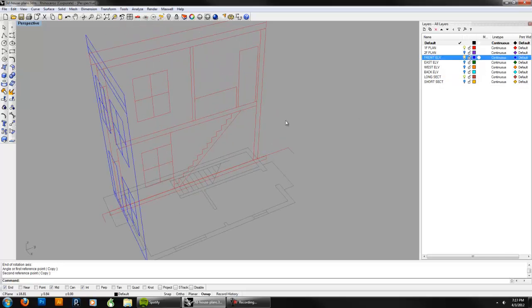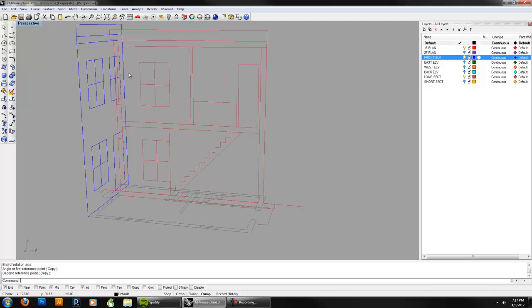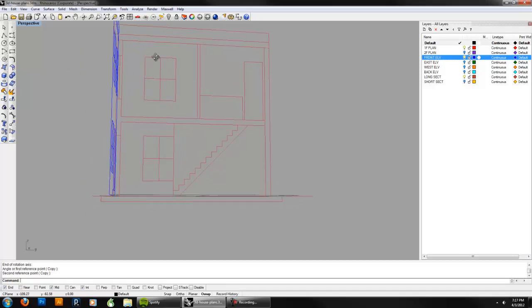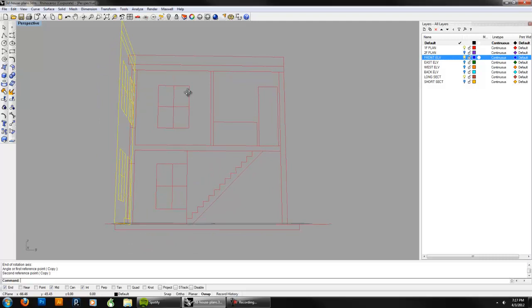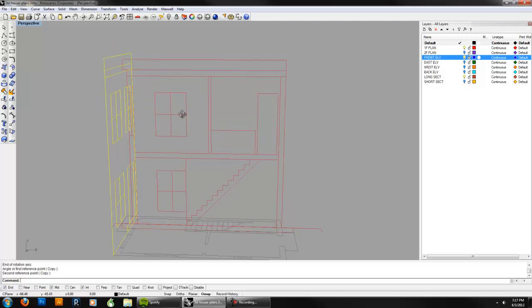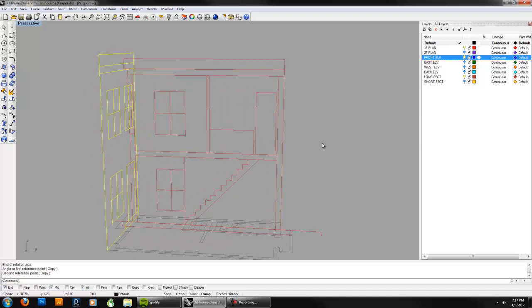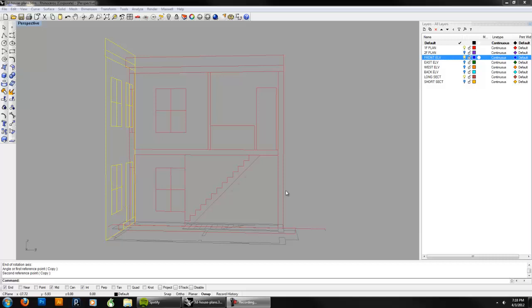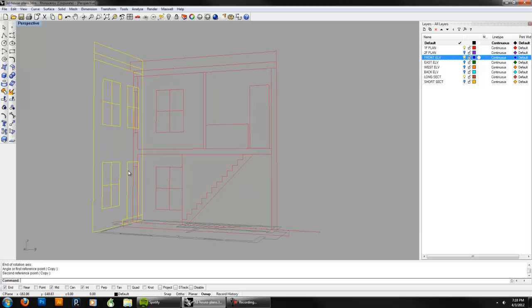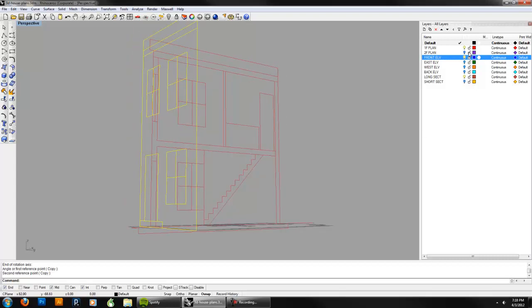And you'll notice that as I turn on my front, it's supposed to align with my drawing, and it does not, so that's a problem. Yeah, so the sections don't quite align. Actually, the problem is the elevations. So the porch thing is here. The floor is actually a bit raised up. So what I really need to do is take all my elevations and lower them.